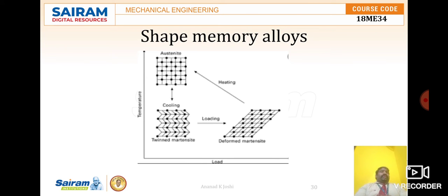And for super elasticity or pseudo elasticity, the shape memory alloy exhibits super elasticity, which is a mechanical type of shape memory. In this case, a force induces considerable deformation in the alloy material, but when the force is removed, the material automatically recovers its original shape without the need for heating. The pseudo elasticity effect is observed when the alloys are strained just above the transition temperature.